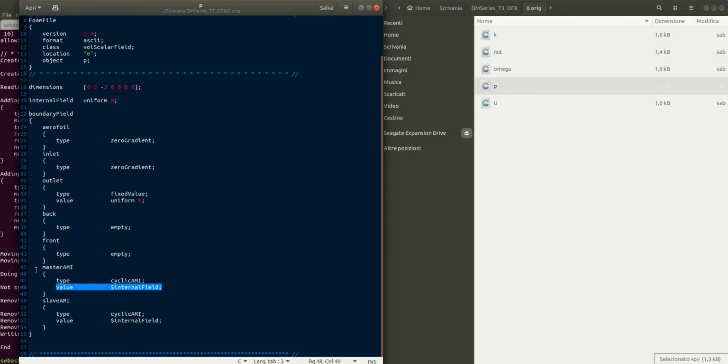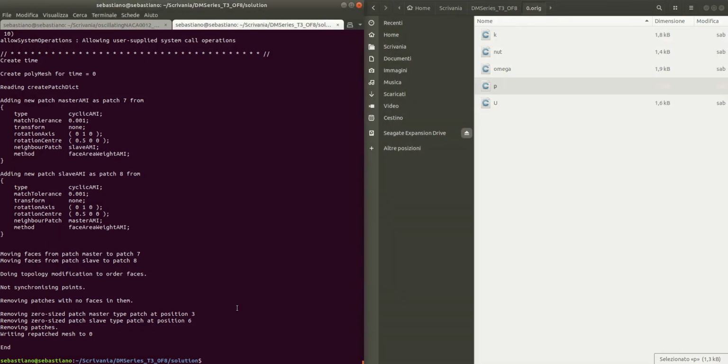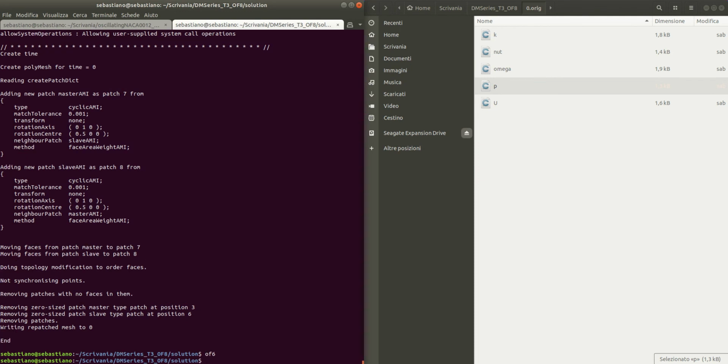And this is the same for all fields, because here there is not really a boundary condition. It's more a way of calculating fluxes across this interface. So what the arbitrary mesh interface does is a non-conformal treatment of the mesh at the interface. So let's try to explain this.